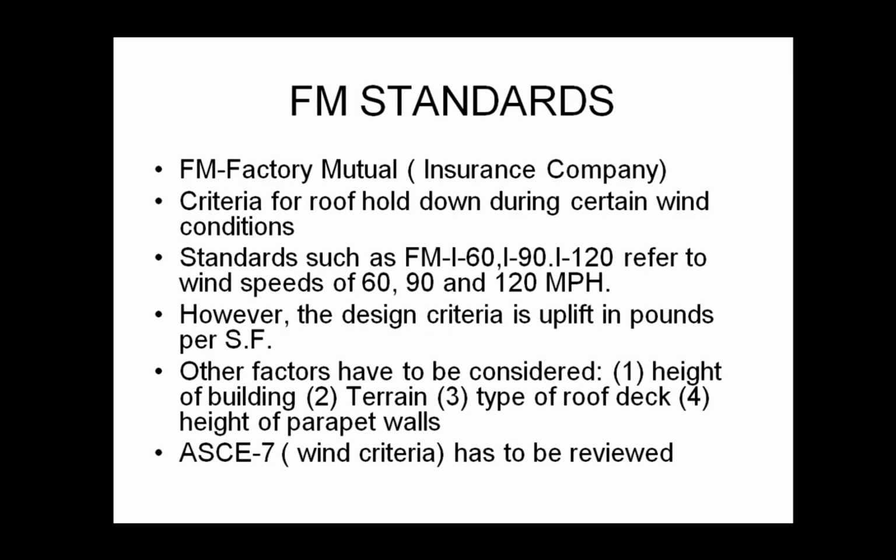Alright, so there are other standards, and these are some of the other standards typical in the industry. The FM standards, Factory Mutual Insurance Company. It's a criteria for roof hold down during wind conditions. And then you'll see an FM and an I 60, 90, 120 basically referring to whatever the wind speeds are that it's supposed to hold up to. And even though design criteria is stated somewhat differently, the testing for the insurance company goes in wind speeds.